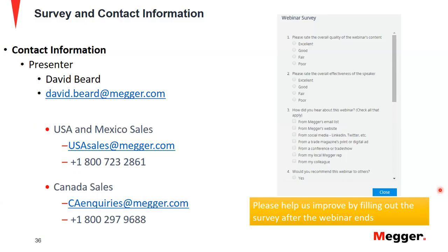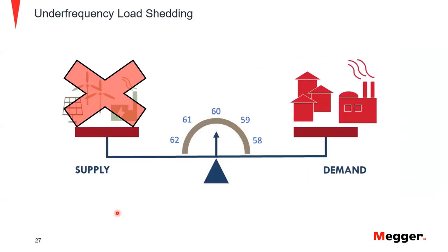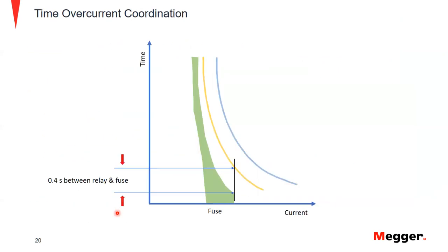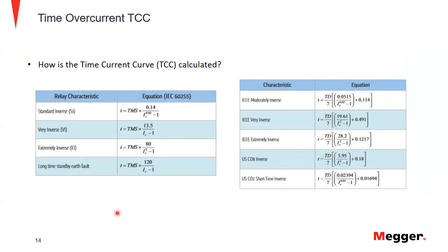All right, beautiful. While I have you, Sugosh, David, if you would mind going to slide 14, I believe they were referring to that one when they asked this. How do I choose between these curves? What does it depend on? I'll wait for David to go to slide 14. So yeah, you would need to perform the short circuit and coordination studies, and then you could use these curves based on your studies in combination with the thermal capacity of your lines being protected.